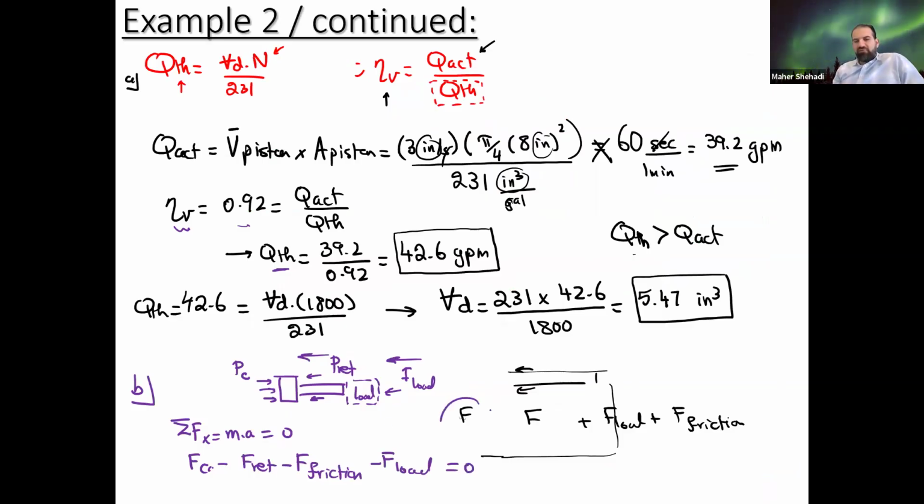Okay, so that's F for the pump. It has to overcome F from the retract. So not the pump, that's just on the cap side. It's pushing this way. All these three are resisting and they're pushing this way. Now, as I've mentioned, we don't have friction between the piston and cylinder. So for now, we'll just neglect it.